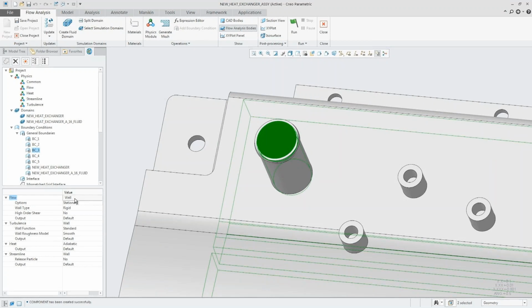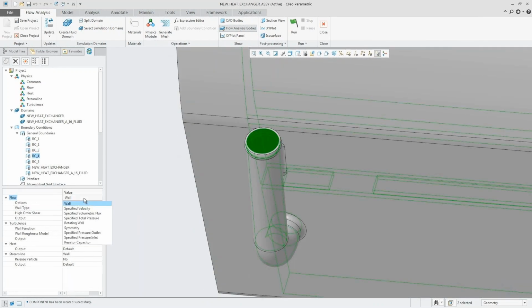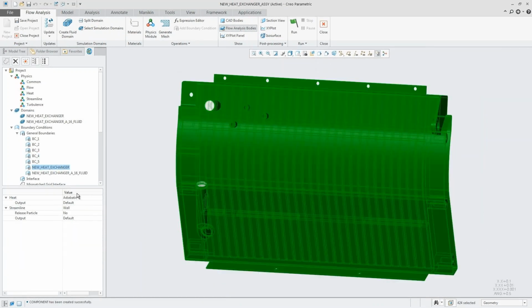We can go through and enter some of the values that we want to observe, such as the inlet flux and the temperature associated with that. There's really a ton of different parameters that can change here, really tailoring the analysis to the exact case that I want to study then. And we can do the same thing down here at our outlet. In this case, I think we're pretty much happy with most of the values down here. Maybe we know that the exchange coefficient and the ambient temperature, or what that's going to be for our aluminum heat exchanger. So very quickly, just go through there, define some of those values for that model.